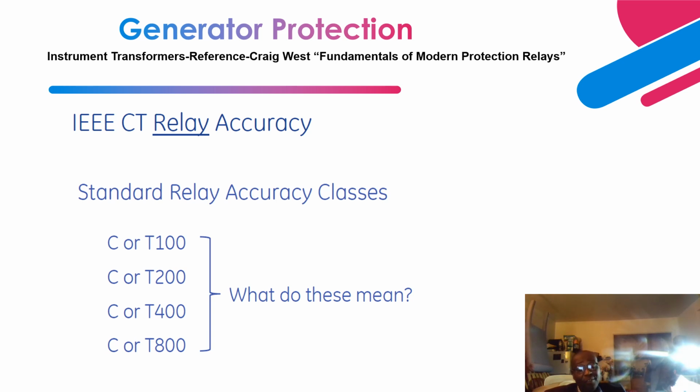You have a 5 amp CT secondary, so 20 times 5 is 100. It means that we can only connect a measuring instrument or a protective relay that has a burden of 1 ohm. So 20 times 5 times 1 gives us 100 volts.